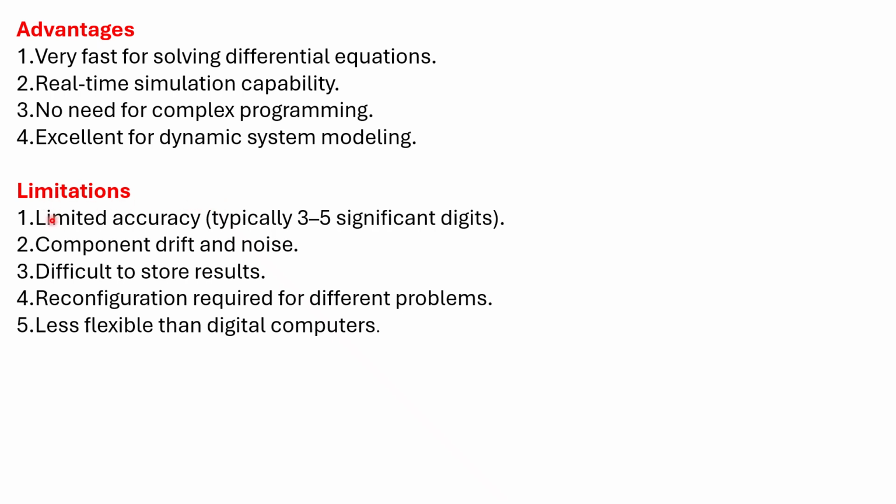Limitation side: limited accuracy, typically 3 to 5 significant digits. Component drift and noise. Difficult to store results. Reconfiguration required for different problems. Every time you have to set the circuit, the equation and its constants. Less flexible than digital.